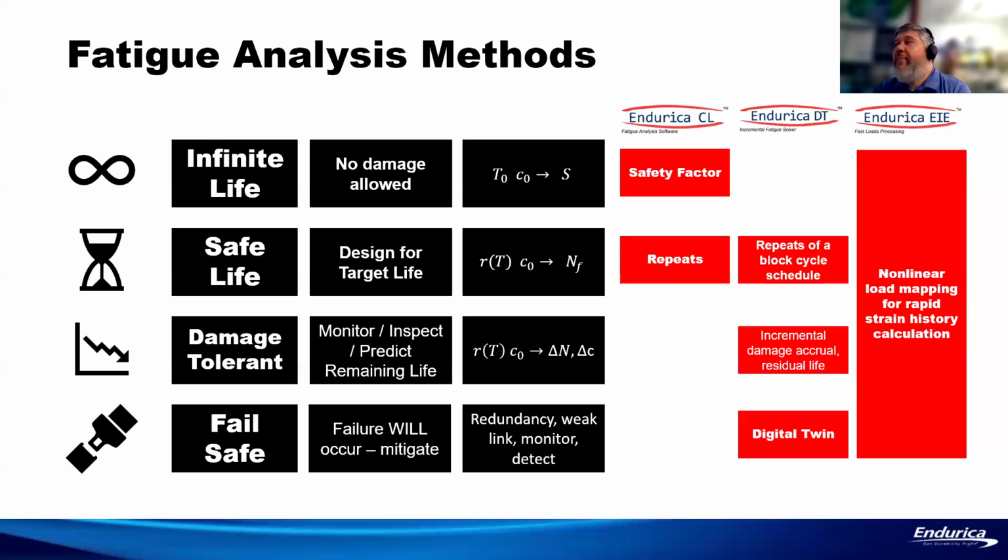Again, back to this idea of scalability. If you don't have a lot of time or budget, this is an easy one to do. You just check and make sure your loads are below the fatigue threshold. You can calculate a safety factor S that indicates your margin of safety. And that's a simple type of analysis we can do.